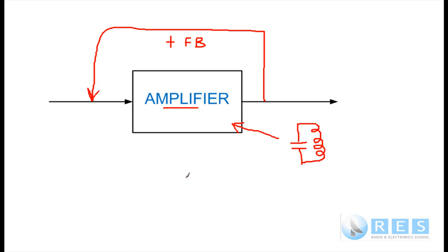When we have all of those things, we have an oscillator, and the symbol for an oscillator is just a circle with a sine wave in it. An oscillator is a source of radio frequency energy, or audio frequency energy if it's an audio oscillator. An amplifier, on the other hand, is not the source of anything. An amplifier just amplifies our signal.